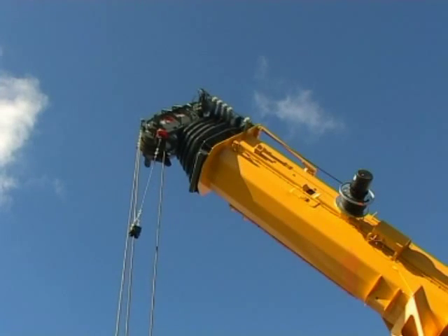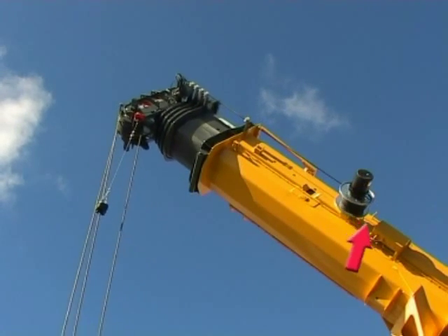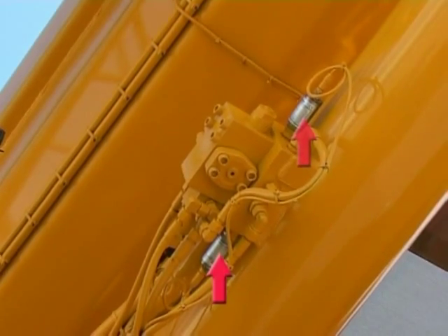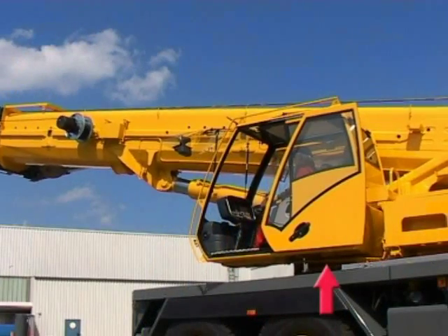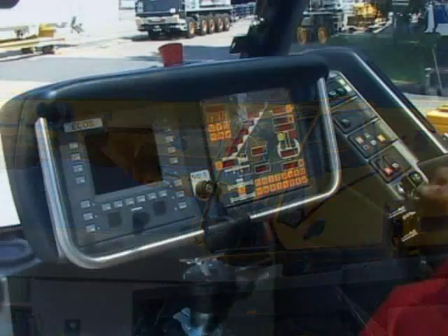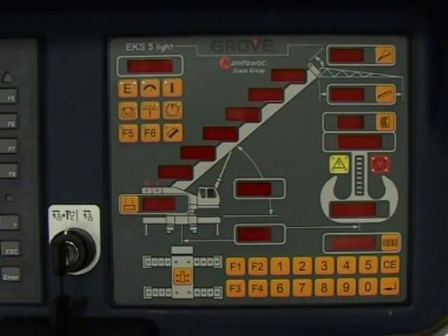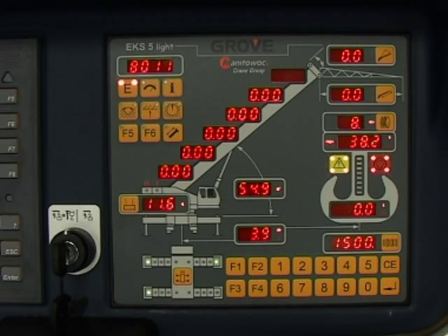The system uses sensors to monitor boom length, boom angle, rated load, and slewing angle, from which the operational limits are calculated. On system start via the ignition switch, a self-test program will run to test the RCI component. You will then see the crane model, software version, and version step shown on the display. The display will then configure automatically depending on the expired time since it was last used.